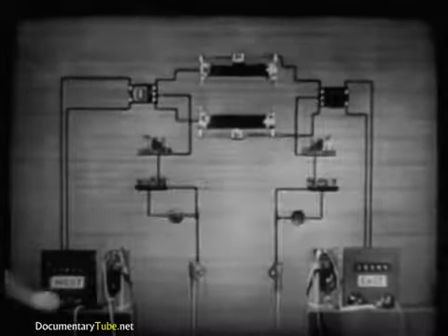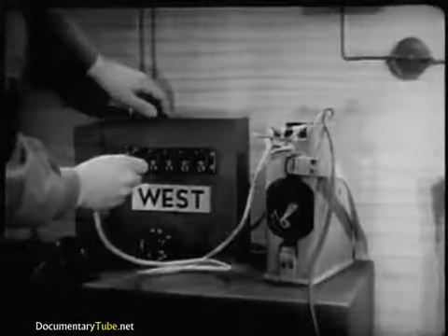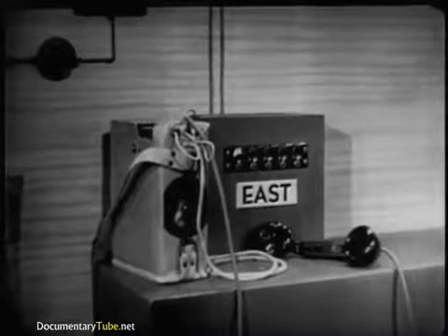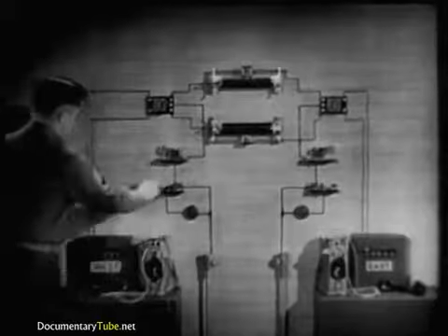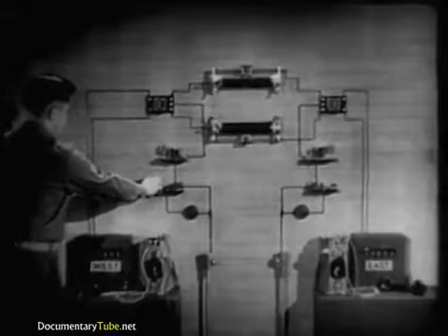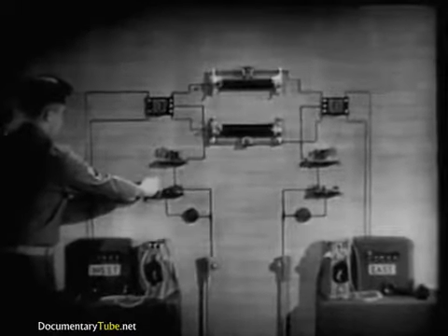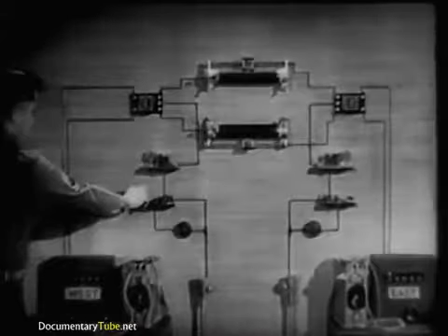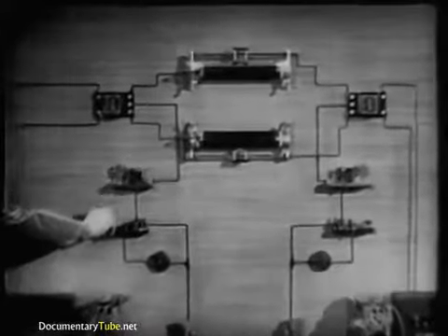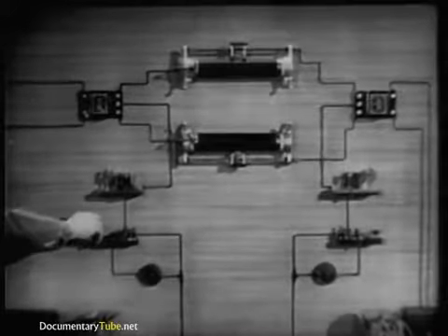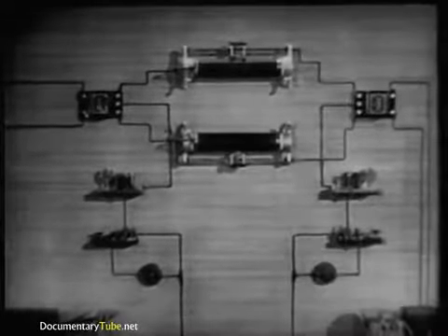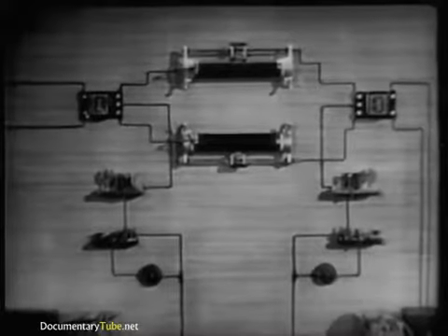The switchboards can still signal each other. The newly installed telegraph circuit can operate without interfering with the original telephone circuit. This new channel is a simplex circuit that may be used for either telephone or telegraph. It is rarely used for telephone, however, because like all ground return circuits, it is apt to be noisy.